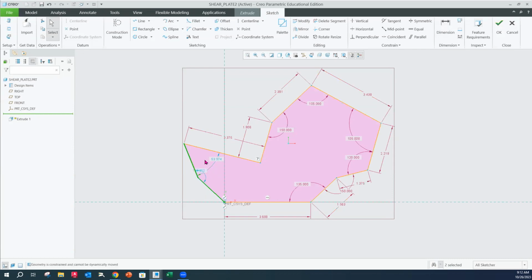So now this dimension I am going to use, this dimension right here, double click. This is going to be 60, enter. And then it's putting in this angle right here. I don't want that in there, but it's going to go away when I put a dimension for the length of this line, which is J to K of 2.077, enter. Okay. So now notice that I have no blue anything.